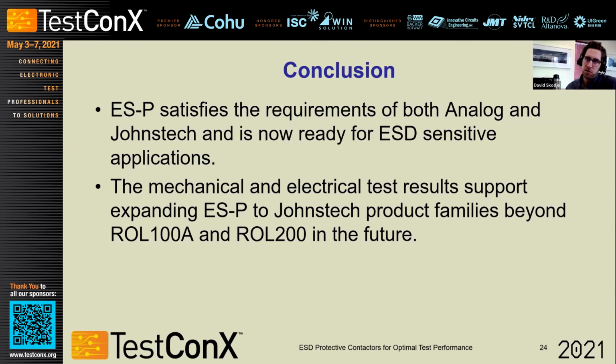I believe it was over a couple years difference in some of the production dates. And if you're talking about the ESD properties, we do our surface resistivity and electrostatic voltage measurement on those to verify that the lots are good when they come in. We have an incoming inspection procedure on the raw material. So far, we've seen consistency from lot to lot based on our monitoring of that.